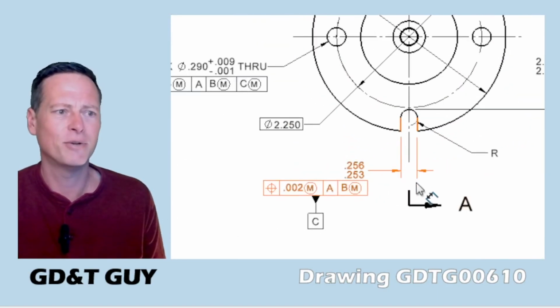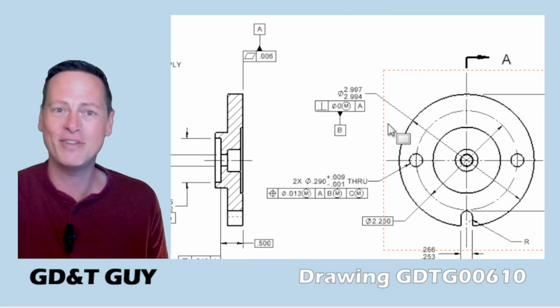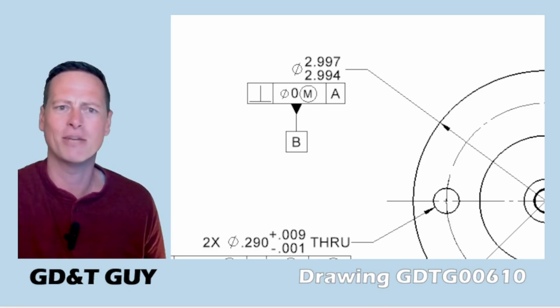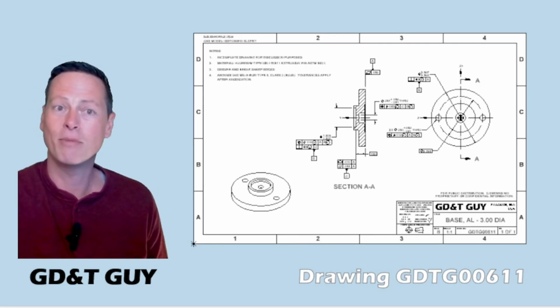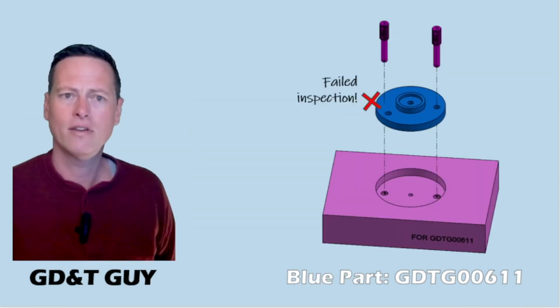Even on the notch here, which will become our datum C feature, we don't have a tertiary datum reference. On our datum B feature, we don't even have a secondary datum reference. And it's understood in the cases of the datum features that we are building from one callout up to the next, establishing the datum reference frame. Fine. But in the process, we are dealing with sub-6 DOF constraint all the time. So maybe if you are comfortable with sub-6 DOF and certain callouts, maybe you can get comfortable with an entire part without rotational constraint. Remember, you have full position control of these holes even without the tertiary datum.